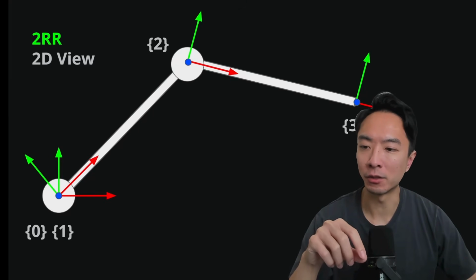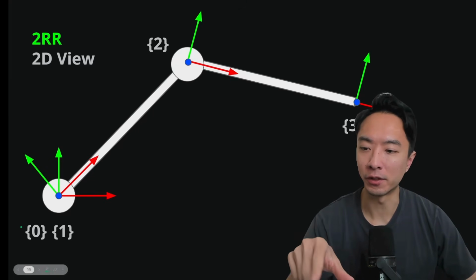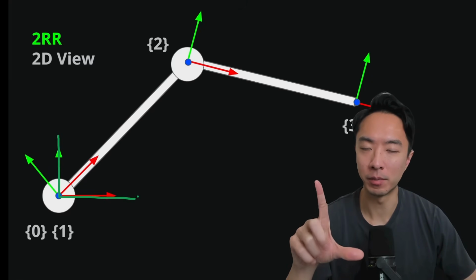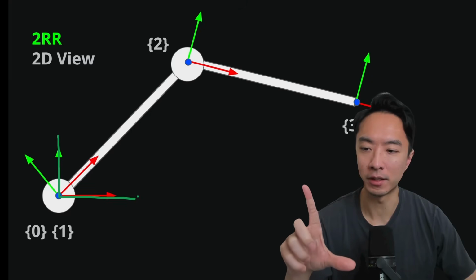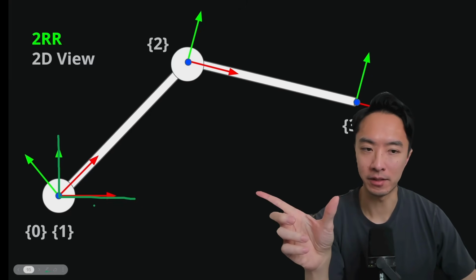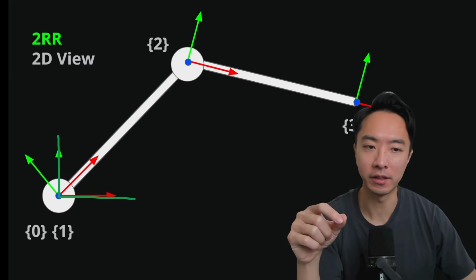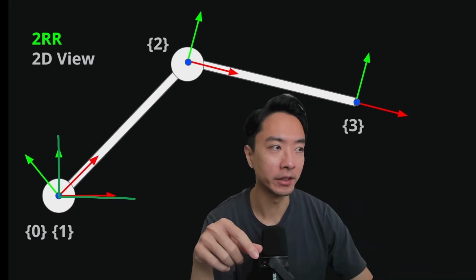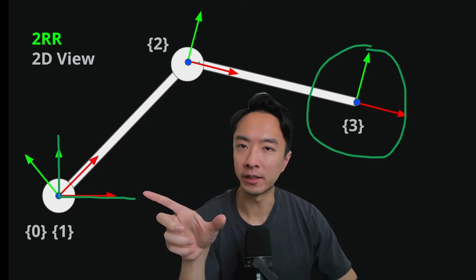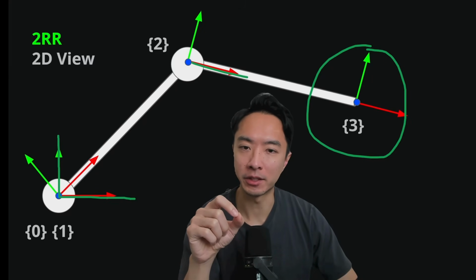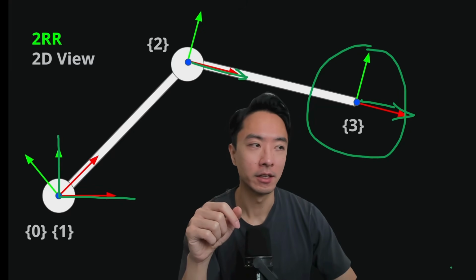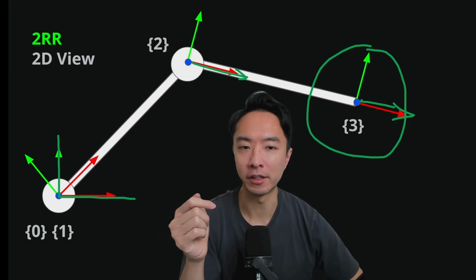And you can see from here, we want to define our 0 frame. So this right here is our 0 frame. We just made it basically orthogonal to the page just to keep it simpler. And then theta 1 is going to be some rotation once there's an angle theta. So we also added a tool end here. You can see this right here, this is our frame 3. And what we did, to keep it simple, is make sure the x-axis is pointed in the same direction. So that kind of simplifies some of the math later on.